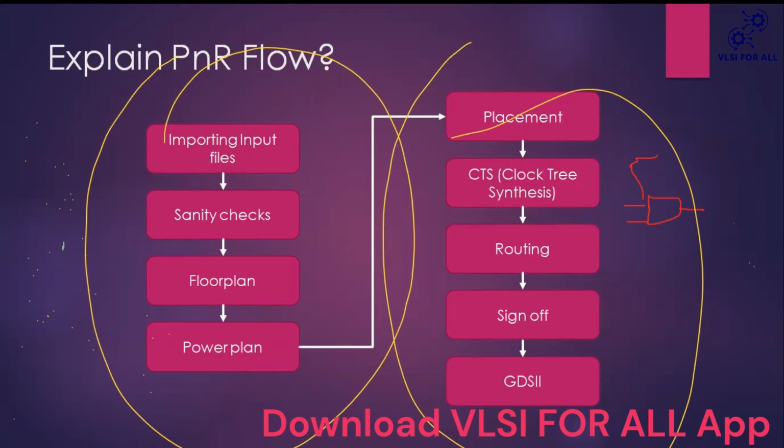We have to avoid these things, but we can't bring the difference to zero nanoseconds. There will be some difference, because one flip flop will be placed at the top right of the core area, and another flip flop maybe at the middle of the core area.